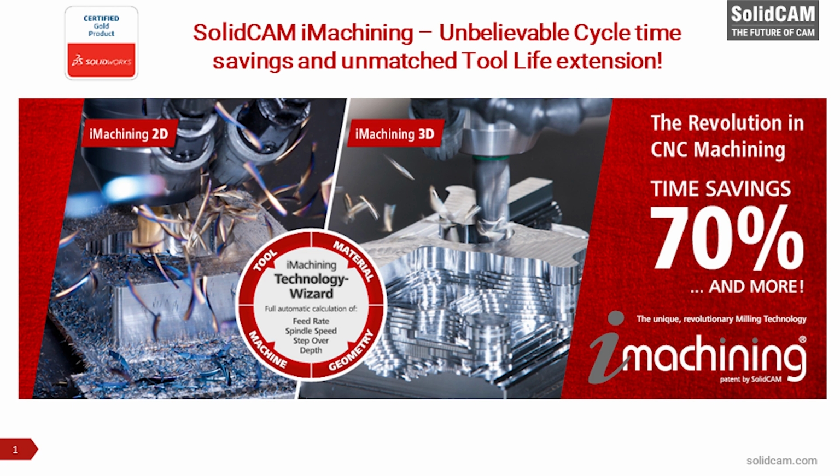What we really know is that the harder the material, and in many cases, the tougher the material, those are actually two different things, the lower the maximum cutting angle needs to be because of the heat generation time that occurs in those.